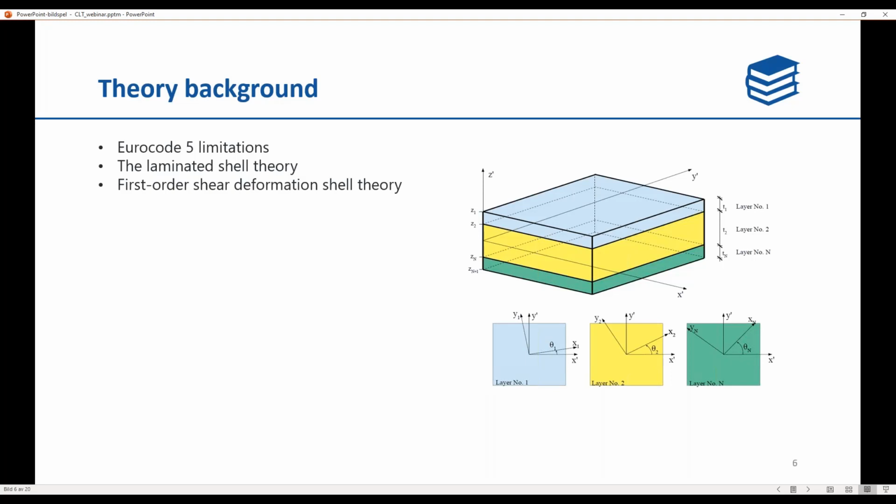It's important for the total deflections since the contribution of shear deformations can be significant, especially in a moderately thick shell, and especially in the case of a laminated composite shell, where the shear correction factors for transverse shear stiffness have an even greater role in the calculation procedure to get the appropriate displacements and stresses. For a CLT panel specifically, this is important to simulate the rolling shear effect.